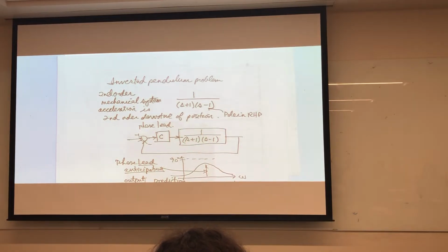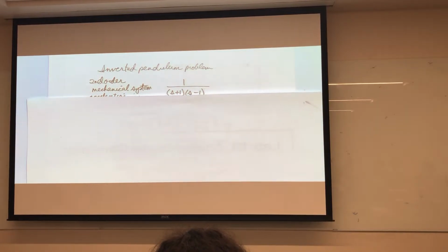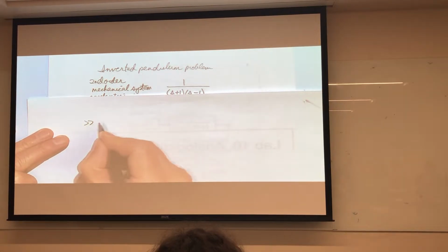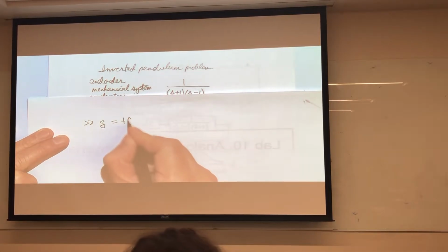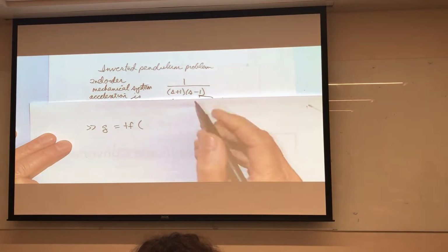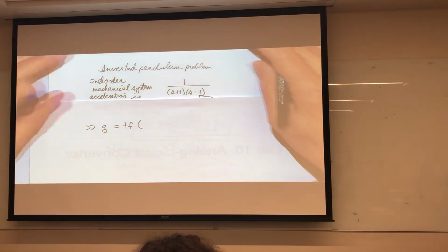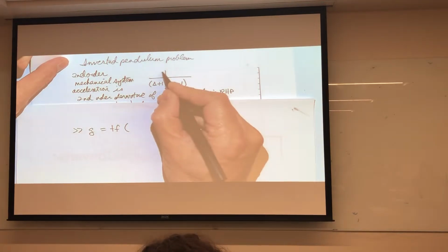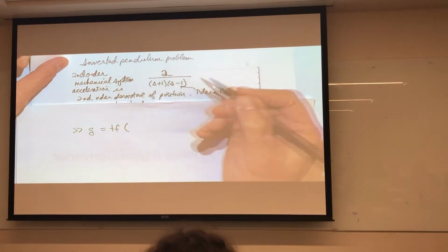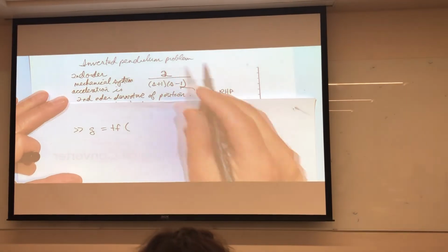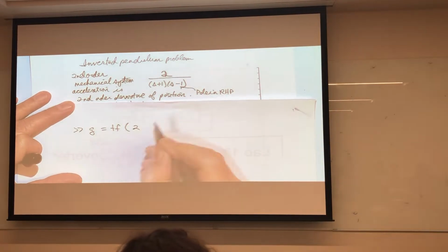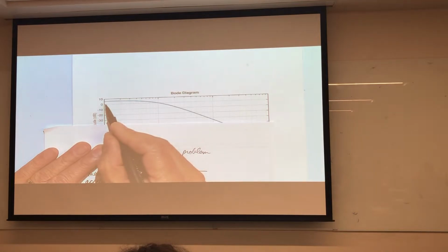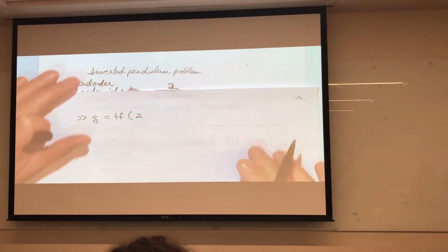If you wanted to do this on your own time, you would say G is a transfer function. Actually, I have a little bit of gain here. I put a gain of 2. Let's change that to a gain of 2, and I know that because this has got 6 dB of gain at low frequency.